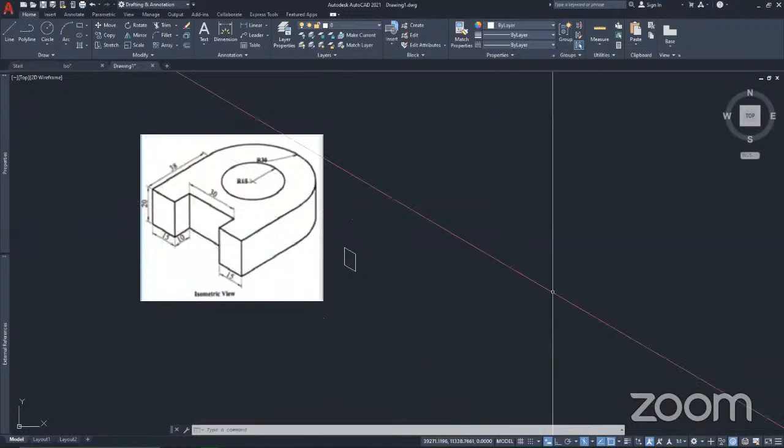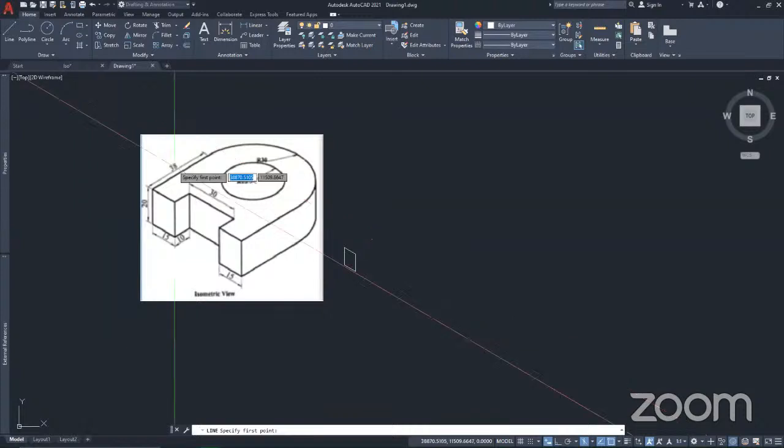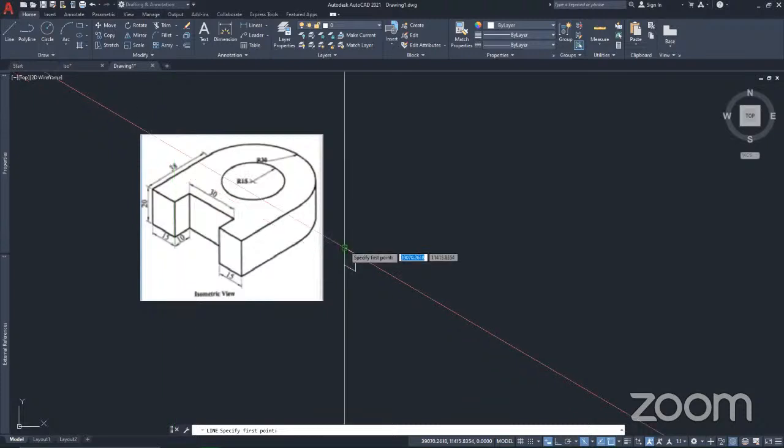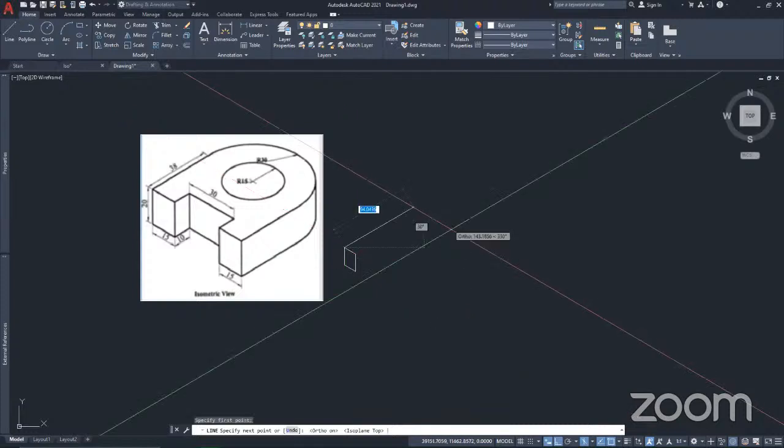Just like an artist, we're going to go little by little and create another line. This time I want to achieve this line of unit 38, this line here. So I'm going to click on this end points like so, and I will need to switch to the top view because that line represents the top. I'm going to switch to the top view using the F5. As you can see, we are currently at the top, and I'm inputting 38.